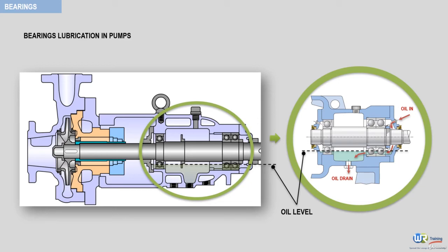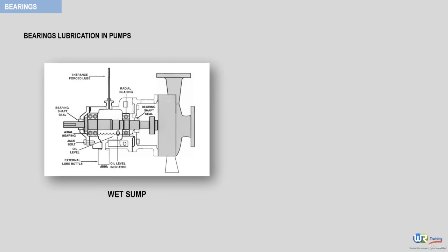Oil mist systems exist to provide continuous and precise quantities of oil fog to the rolling assembly. These systems normally employ an additional pump, an atomizer, and a filter. These systems are gaining popularity in hot applications or with heavy thrust and radial loading. The oil fog is sprayed into the bearing chamber with either a wet sump or a dry sump.